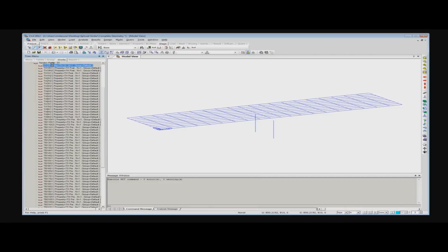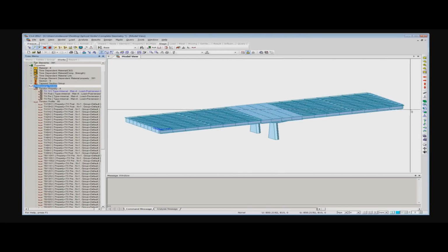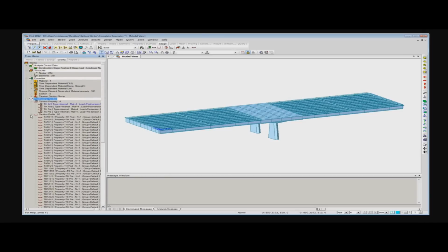So let me remove this one which I defined. I don't want to make confusion. So totally we have 80 tendon profiles, and the reason for having these 80 is that we have defined the pre-stressing. Let me show you again. On the left side and right side, as I mentioned, they are like a precast pre-stress. So we need to define tendon profiles for them, as well as we have post-tensioning tendons, which go through the entire bridge and make it a continuous structure. So totally we are coming up with the 80 tendon profiles, which you can see here.